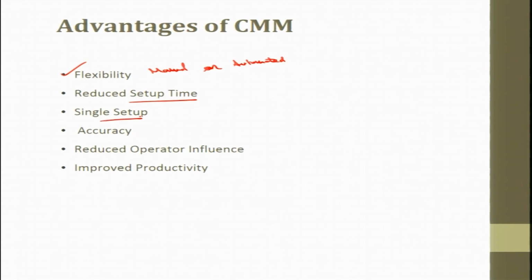The single setup is there, accuracy is high. Reduced operator influence is there, because the operator is not actually touching or making the workpiece or the probe move. It is moving by itself. He is just trying to control the joystick. Once he defines the coordinates, the origin, and the plane, once the plane is defined by our probe, it has fixed that plane. This is the reference plane.